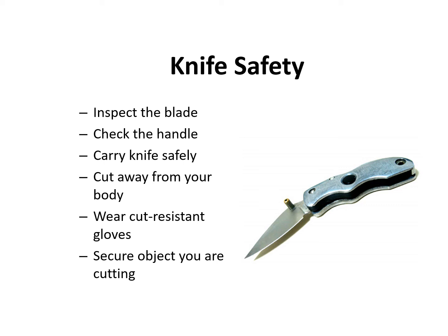Always cut away from your body. Wear cut-resistant gloves on your offhand. Secure objects you are cutting with a vice grip or in another way. Do not hold the object with your other hand. Many knife-related injuries occur when a knife slips and cuts the hand holding the material being cut.